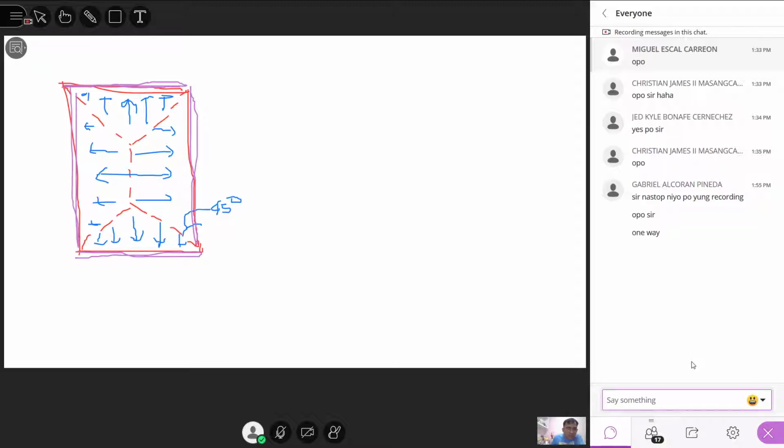So in that case, we can calculate the load directed towards each beam. The equivalent weight is used to convert this trapezoidal load into a uniform load. It will be equal to WS over 3 multiplied by (3 minus M squared) over 2, where M is simply equal to S over L. This is S and this is L. That is the equivalent uniform load.